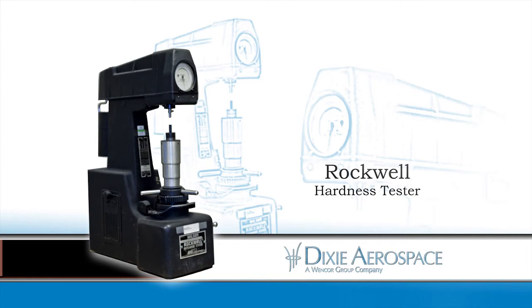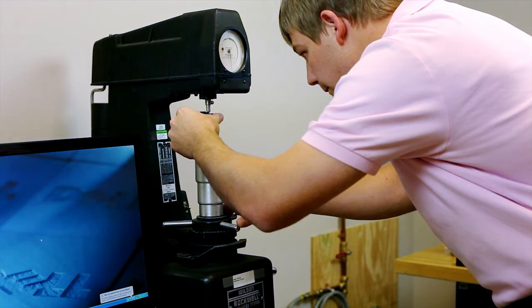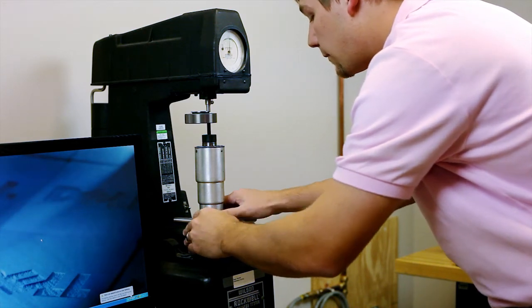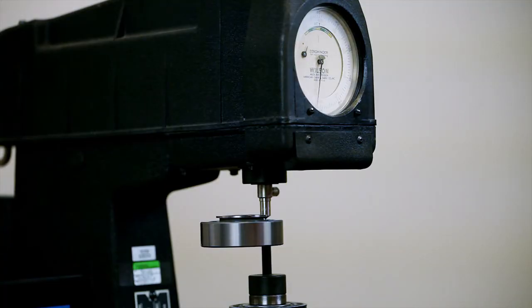Dixie utilizes a calibrated hardness tester to test for surface hardness requirements. This machine is used to collect preliminary hardness data before the components are sent to an independent metallurgical testing facility. Each part sample is checked in either the HRC or HRB scales. These hardness checks help the engineer determine heat treat conditions that may exist. The heat treating condition is an important feature which helps indicate what type of environment the parts are intended to be stable for operation in.